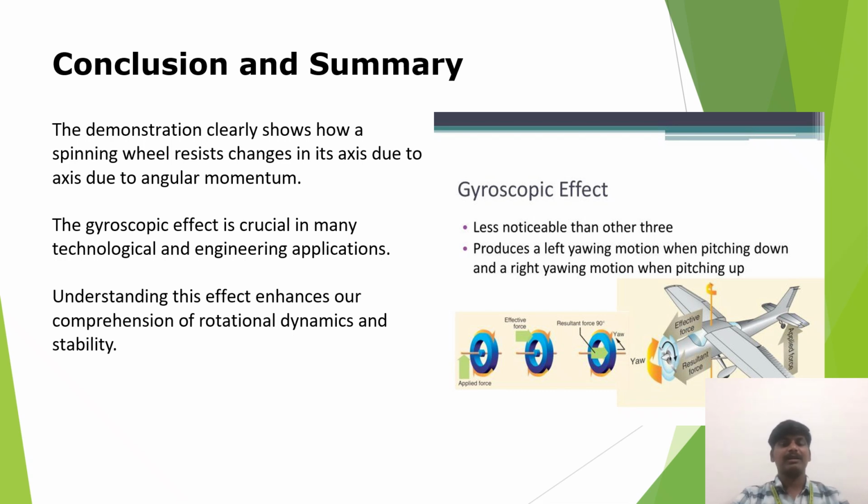The gyroscopic effect is less noticeable than the other three. It produces a left yawing motion when pitching down and a right yawing motion when pitching up. Effective force in aeroplanes.